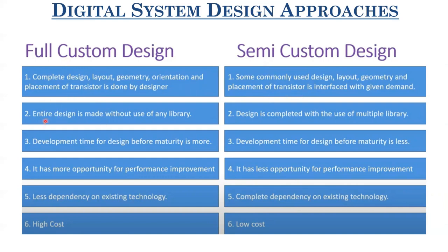Also, in full custom design, you do not need any library. However, in semi-custom design, you have to use a library, and not only one library, multiple libraries. Then, development time for design before maturity is more for full custom design. This will become clear when we discuss the next slide. However, development time for design before maturity is less for semi-custom. Since most of these designs are automated, you can expect that the development time will be lower here, right?